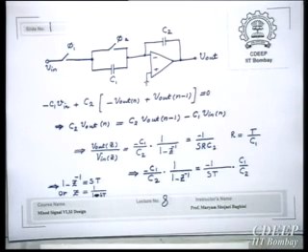Magnitude of ST is small means that the sampling frequency is quite enough compared to the maximum frequency included in the bandwidth of the signal. So that is a very interesting implementation. And there is one more implementation and approximation, which is bilinear. Actually, bilinear is, I would say, the best transformation and approximation we'll see. And for this mini project also, I ask you to use the bilinear transformation for this conversion.